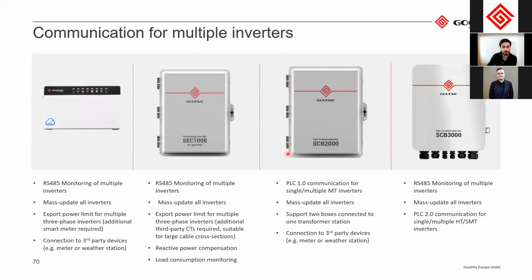Sorry, this slide before the quiz. For multiple inverters, we have a bit larger boxes, and the standard one is the ET Logger Pro. This is a data logger that you can connect up to 60 inverters to it. And from this one, you can then monitor all inverters, and in case you need to do a firmware update of the inverter, instead of going to every single one of them, you can do it directly from this one, and this will send it over to all of them.